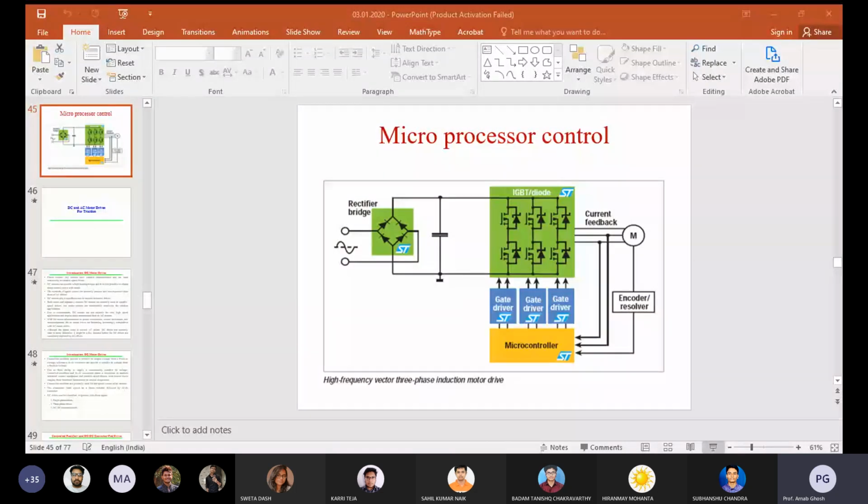Instead of other kinds of DC motor, such as the shunt motor or compound motor, the DC series motor is suitable for traction. But right now other types of motor are also being used for traction purposes. The primary things are the availability of the source and what type of load you need to overcome. Based on that, you pick your motor.